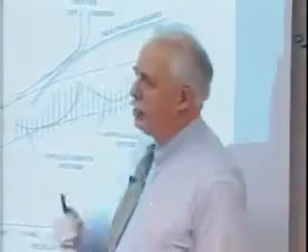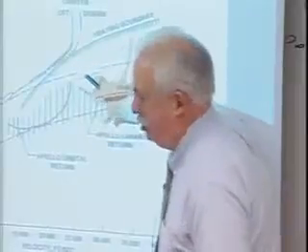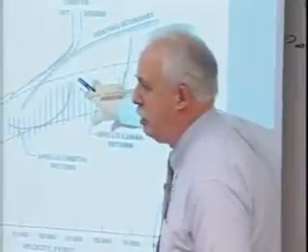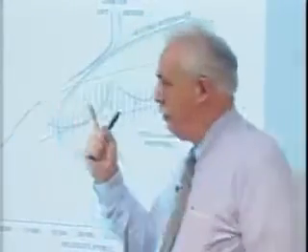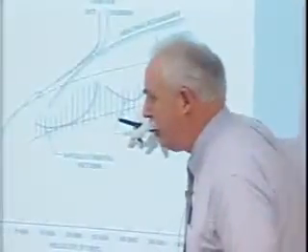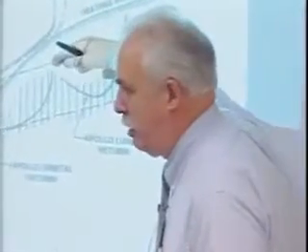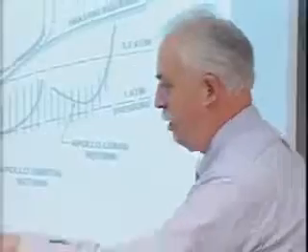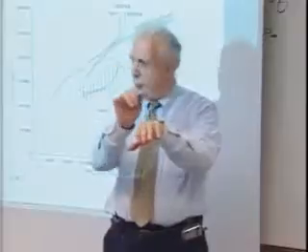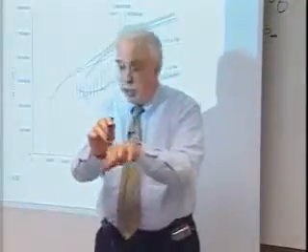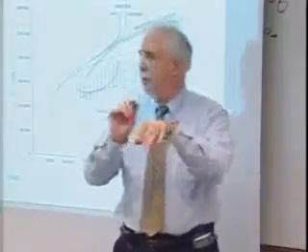Oh, this is the flight mechanics, and I'm not an expert on that, but basically, this portion was designed to capture. If you don't capture, you're gone for another 2 weeks. And you didn't want to get beyond 20 Gs, because nothing would take beyond 20 Gs, obviously. You didn't want to skip out. This is a linear plot. You're looking at an atmosphere, and you're coming in at high speed. You want to make sure you're captured, not too steep, or you're blown apart. But if you miss, you're going for another 2 weeks.